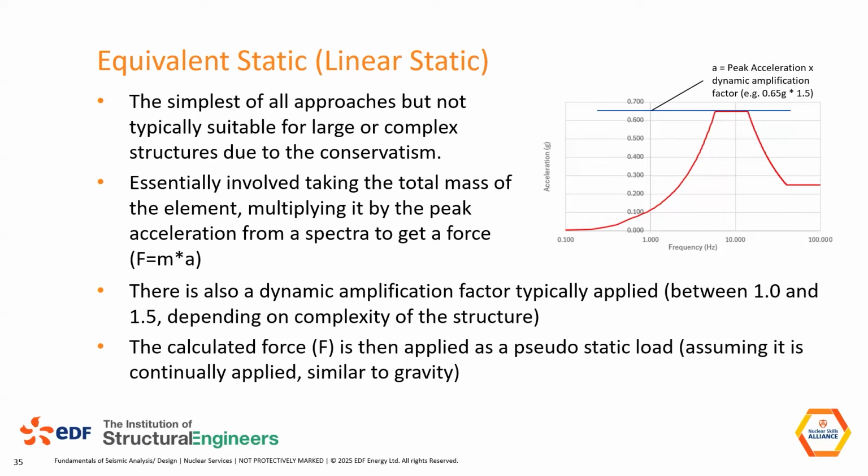That is to do with higher order modes. And for a simple structure, you can take that as 1. I think for base reactions, you can take it as 1. But for design of elements in more complex structures or structures with multiple supports, it's recommended to increase that. I think 1.5 is normally what you've done. So it's very simple, but it's very conservative.